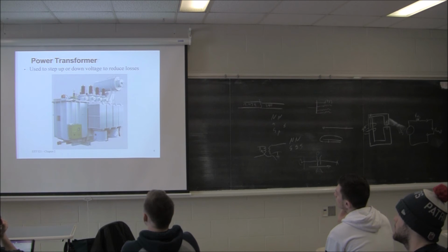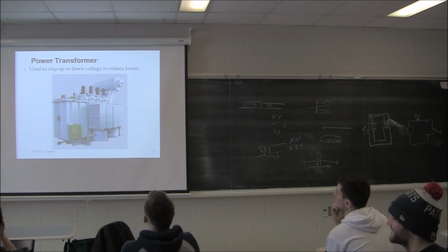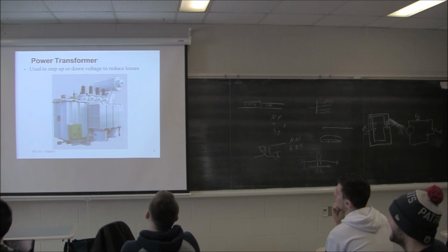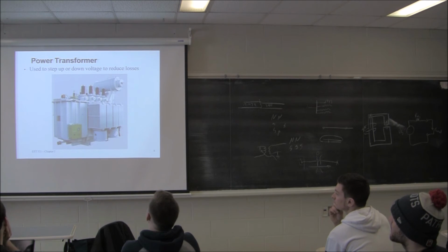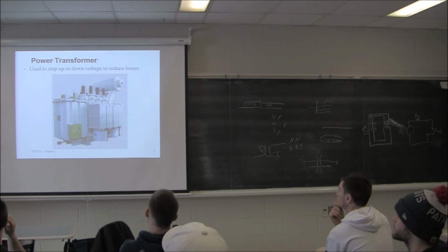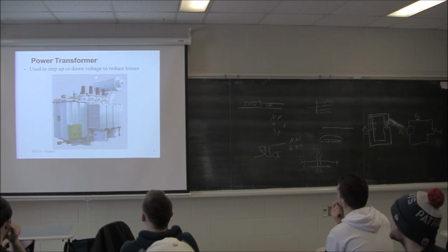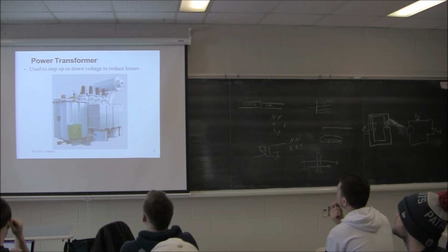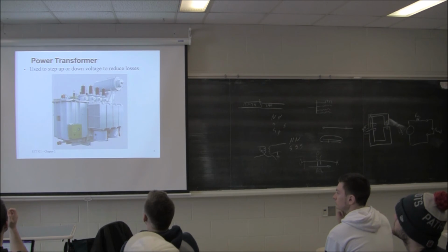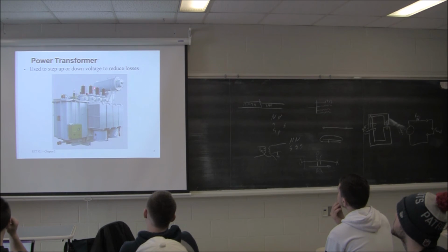Can you tell if this is a Y or delta transformer? Is it a Y or delta, because there's a neutral? Does delta have a neutral? I can't remember which one has a neutral. Y has a neutral, and this has how many bushings? If it's a delta, you only have 3 bushings, right? A, B, C, and then the neutral. So this would be a Y. I can't tell. I can see 1 over here, 2, 3, but I don't know if that's another one. It's hard to tell with this image.